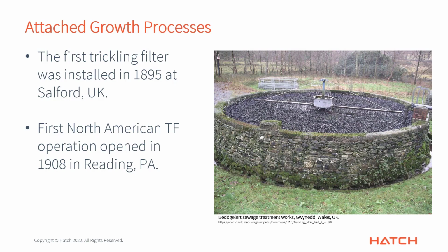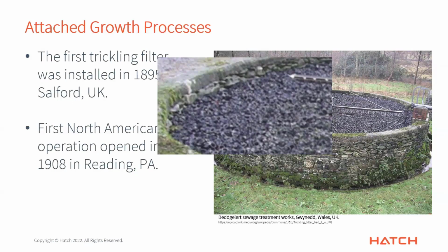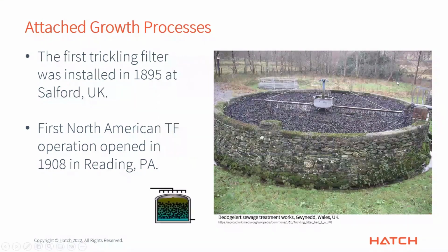And then, you're of course distributing the wastewater on the top there, and it percolates down, and there's a drain through the bottom to collect the treated water. Now, this particular one, you can tell by looking at it, and I apologize, it's not a great resolution here, but you can see that this is actually modern plastic media, these kinds of rings here that are part of this particular process. So not uncommon to find these types of systems still in use throughout North America and quite a bit in Europe still.